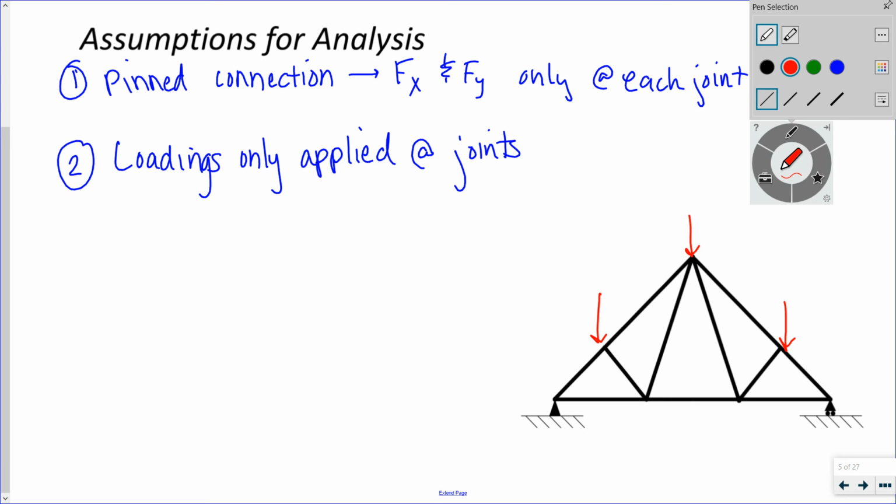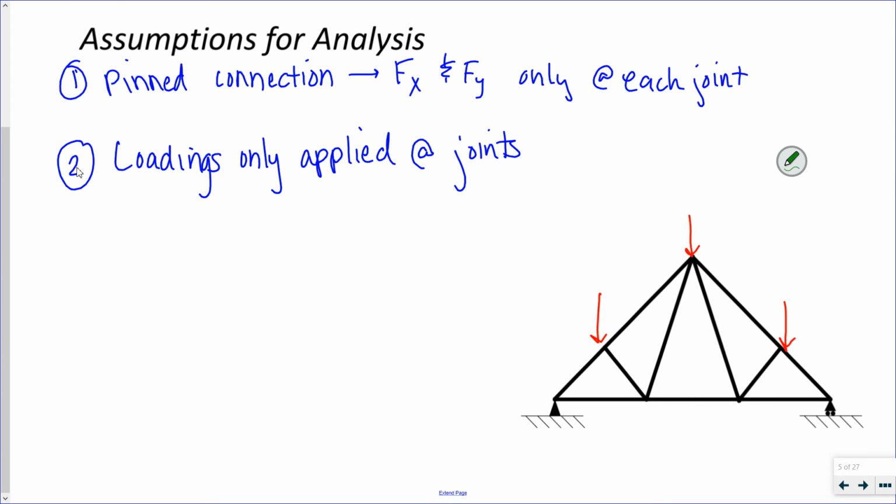If I were to apply a load between joints, that would cause bending in my member, so I don't want to do that.